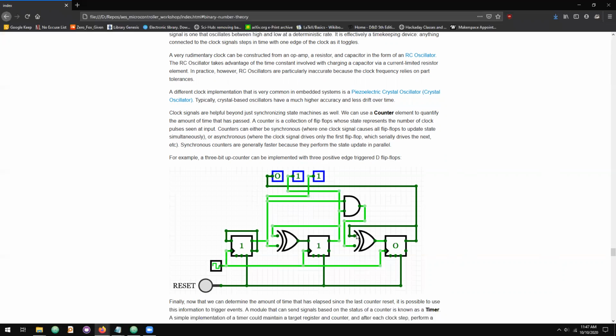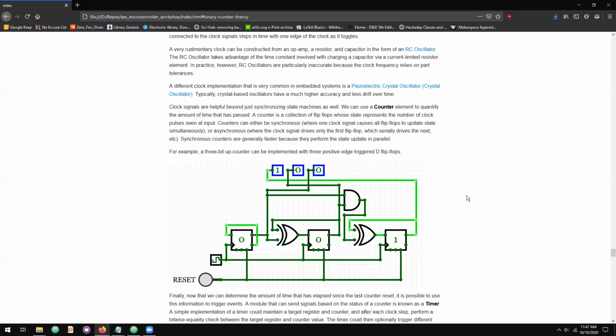The outputs from this system, which I've represented up here, you can also feed into a hardware register. But basically, when this clock toggles, we add 1 to the system. What that means is we have something that counts every time this clock signal toggles, at least for this circuit. So this combination, a clock signal, some combinatorial logic, and a hardware register, we can use to represent counters.